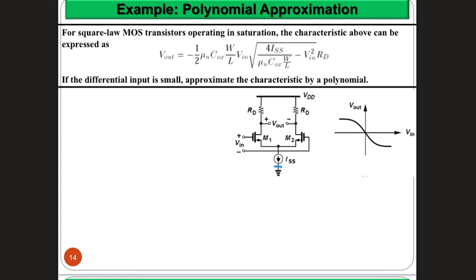The important part here is, now this is a nonlinear relation, but we really need to work with a polynomial expansion. And typically we stop, for example, at the third order, right? So how can we express this as a polynomial using Taylor series expansion or whatever? Simple here, if you assume that the input Vn is small compared to this term, okay? So if you assume that this term is much smaller than this term, you can actually, in that case, approximate. So the root of 1 minus x can be approximately written as 1 minus x over 2. Okay? Only if x is much smaller than 1.